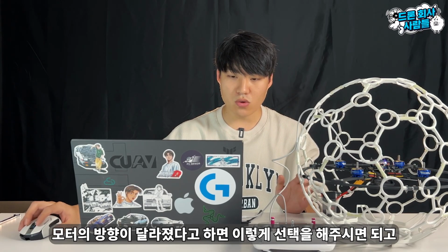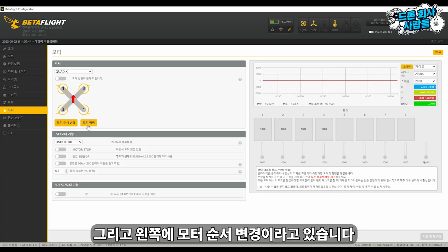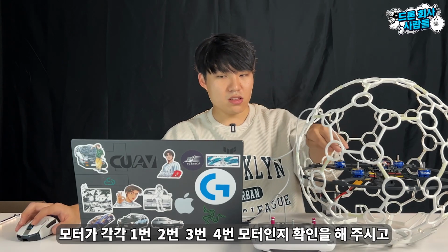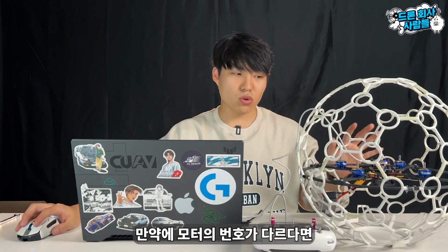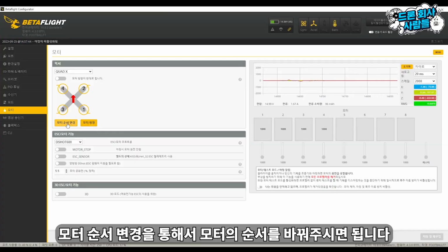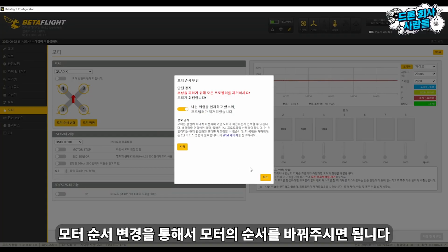If the motor's direction has changed, you can select it like this, and there is a change motor order on the left. Please check if this motor is number 1, 2, 3, or 4. And if the motor number is different, you can change the motor order through the motor order changer.